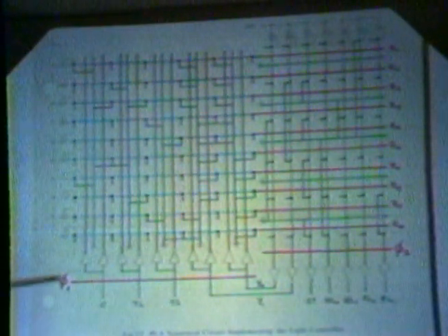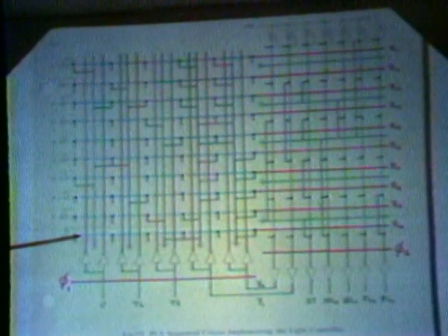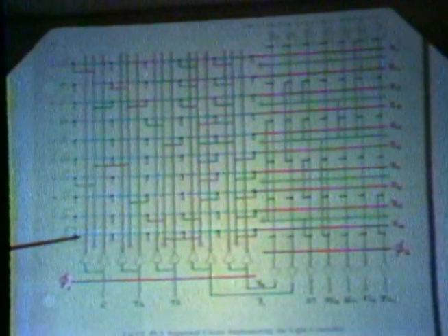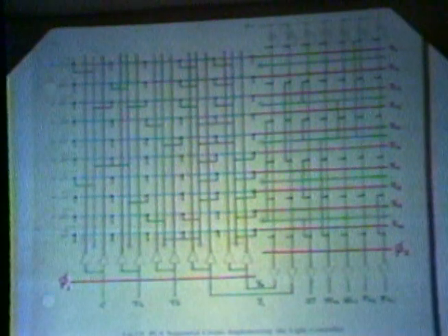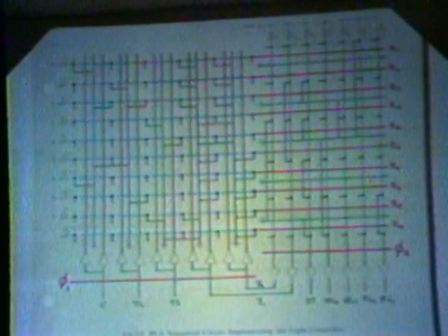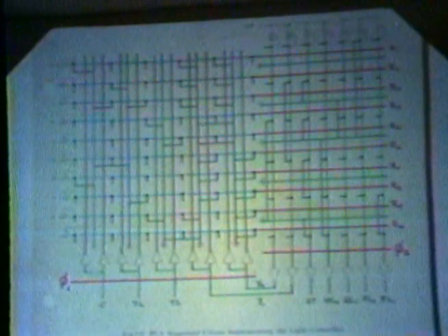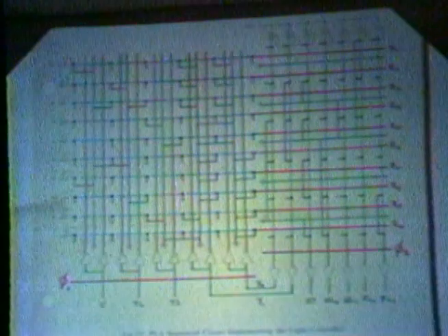But along with that increase in size, the metal lines on each of these NOR gates get longer. And as those get longer, there's that much more stray capacitance on those nodes, and so it gets a little slower. But what might really get you is that if the logic is complicated for that many inputs, then the number of product terms you need to design that function may grow also.